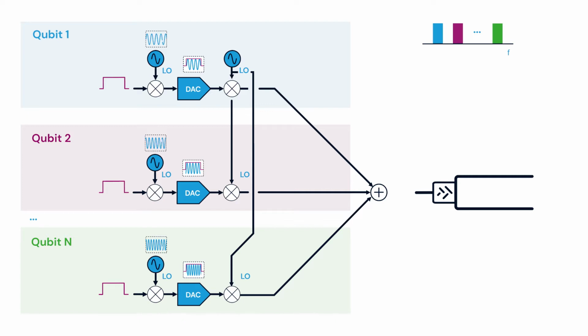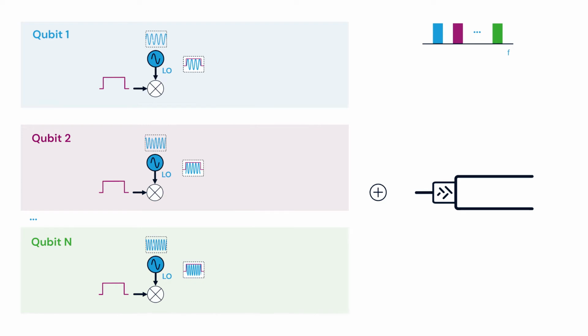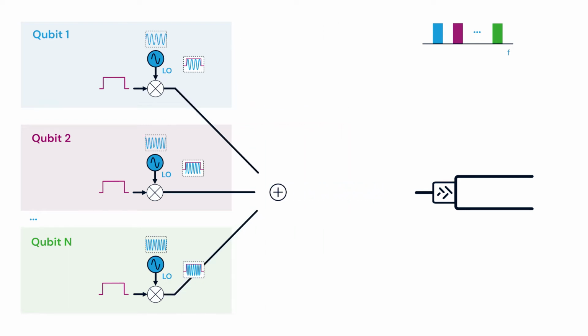We apply the signal to a digital-to-analog converter that converts the signal in the analog domain. We then multiply the resulting signal with a microwave high-frequency oscillation to move it to microwave frequencies, so that the generated pulses match the Larmor frequency of the different qubits. In that way, we obtain a spectrum comprising the spectral contents for each of the qubits. Since the Larmor frequency of each qubit is slightly different, we can use a single coaxial line to transmit this signal to our quantum processor.